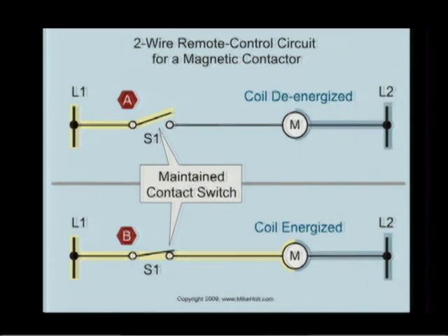And you have to say, okay, sit back, look at the logic you have here. You can tell that's not the motor, that's the control circuit controlling the M coil that closes the main contacts that go from line 1 to T1, line 2 to T2, line 3 to T3, and that's how it works. So you have to get a little bit more experience. But somebody who has a lot of experience wouldn't have been confused. So they don't say, why are you confused? It's, come on, look at the circuit. But we don't have the knowledge sometimes.